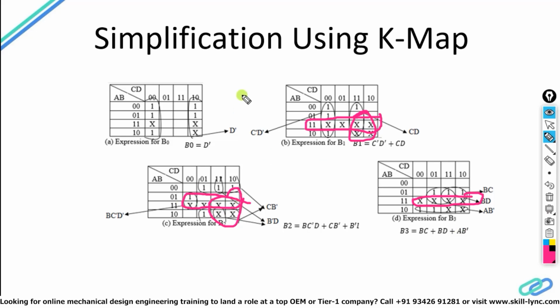Okay, we are here just to make use of don't care for this bigger pair only, nothing else. So this is 4 here, 4 here, 4 plus 4, 8, which means you can easily make a frame out of 8 ones, that is an octa pair. Okay, now what will be the answer?